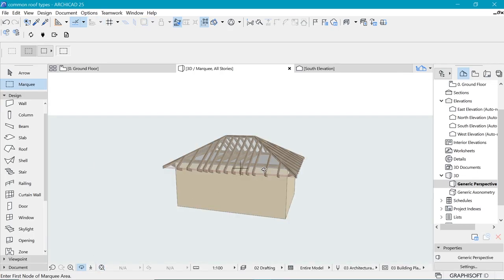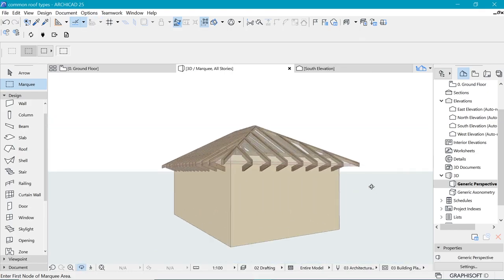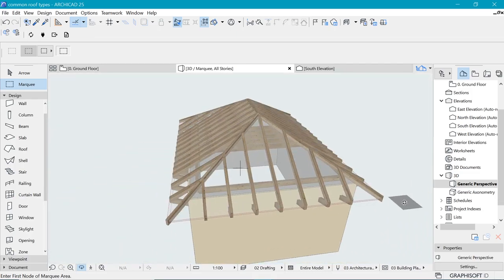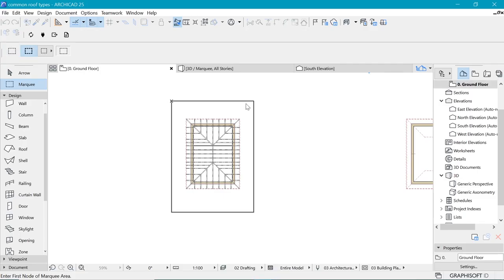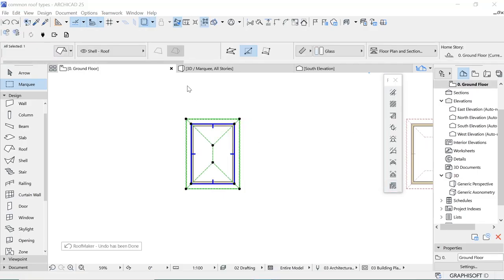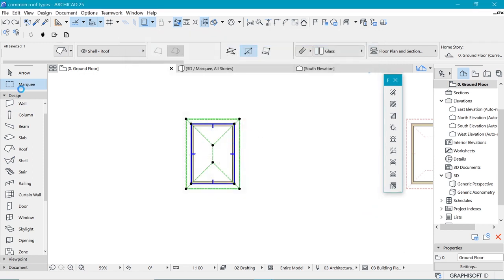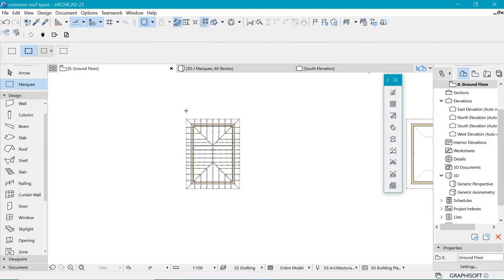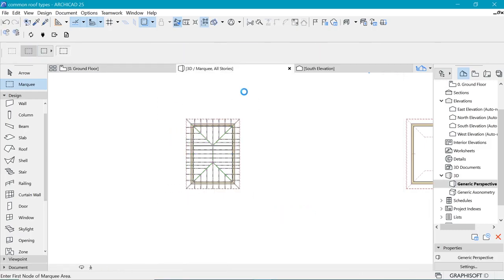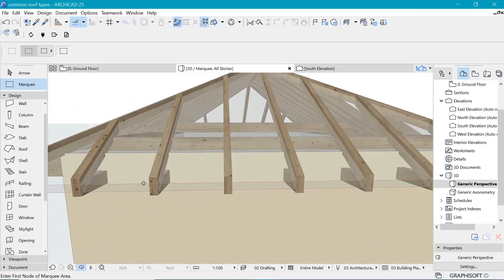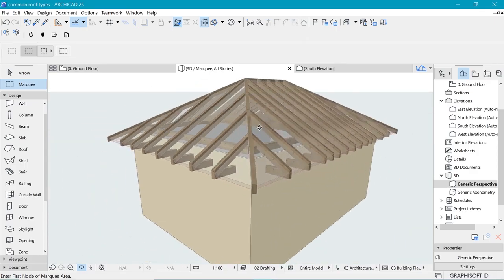And there it is. So for starters, we have ourselves a soffit which is at an angle. Perhaps you want that, perhaps you don't. And I think I don't like that rafter is at an angle, so we'll just go back and change this to 0 instead of 20. And when we say okay, now it should create for ourselves a pretty neat soffit which should be perpendicular to the walls. I think that looks much better for my case, but as well you can choose whatever you want.